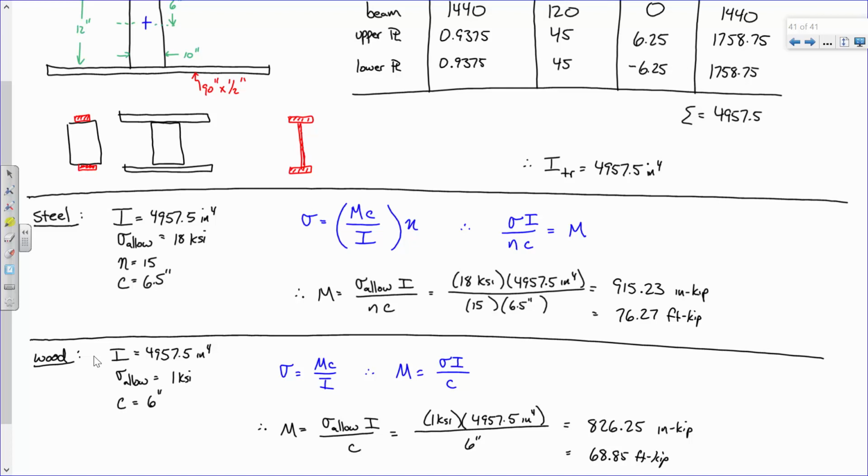For you civils who decide to take steel design, one of the things that we'll talk about is different types of connection scenarios, like bolted connections and welded connections. For these connections, we'll have a variety of different design checks that we'll perform, like how much load it can withstand under this state and under that state. And what you'll find is that one of those is governing the design and the rest are fine. And that's, I would argue, probably going to be the case in a lot of machine element design or steel design or any of these types of engineering computations. Does that make sense? All right.